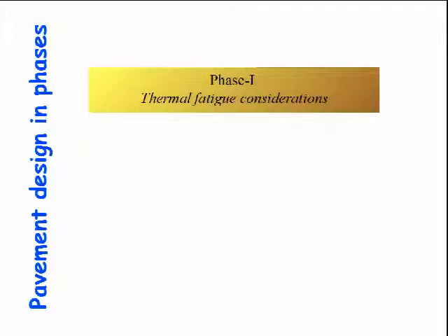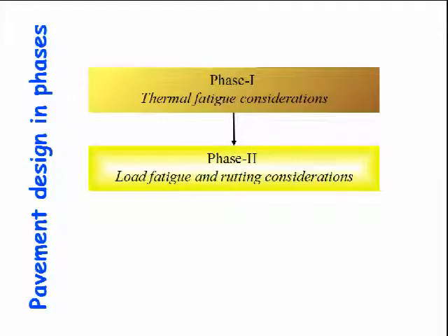So therefore, I could place this as phase 1 of my pavement design, where I am only taking a decision based on the mix design, and then I come to phase 2, where I have to think of the load fatigue as well as the rutting, which obviously are related to the thickness.